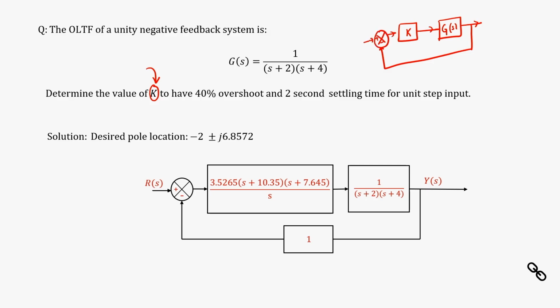This is the block diagram. So, you can see in this block diagram what were we trying? We were trying to find out a K. So, what is this controller? This is a P controller, right, because here input is error signal, output is just proportional of that error signal. So, this is a P controller.